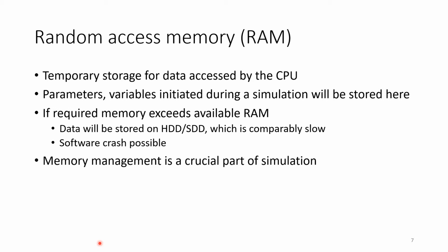So this is why memory management is a crucial part of simulation. Before starting your simulation, you have to imagine, okay, how much memory do I have available? How large will my arrays be? Because this will also, from a hardware side, limit your mesh size.